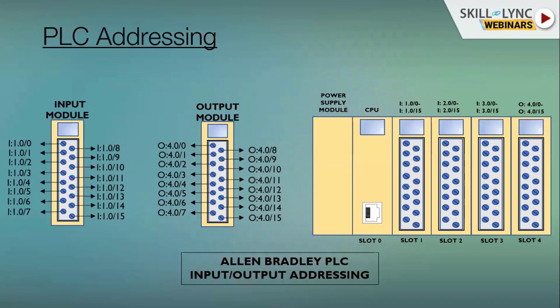I have shown here one of the reputed PLC brands, Allen Bradley PLC addressing. You can see on the right side a modular PLC with the power supply module on the leftmost side, then the CPU. Next to that, I/O modules are put together one by one. The location of inputs and outputs in a PLC system is known through slots, locations which are made one next to each other.